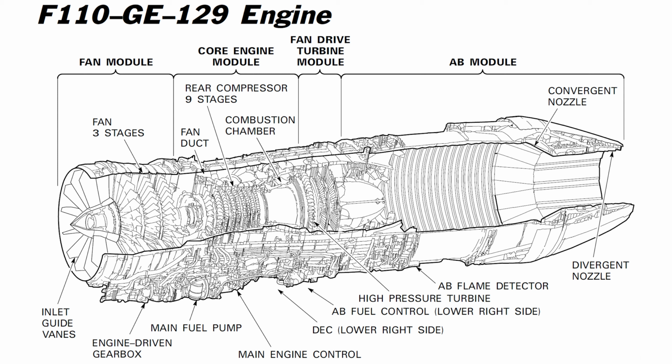In primary mode with the landing gear handle down, the nozzle is greater than 80% open at idle and closes as throttle is advanced. The nozzle controls engine thrust for optimum performance through the flight envelope and maintains fan stall margin by varying the nozzle area. The exhaust nozzle consists of two sections. The divergent nozzle floats freely and moves in conjunction with the convergent nozzle. The convergent nozzle is controlled by the convergent exhaust nozzle control, which is actuated by a high-pressure bleed air motor.